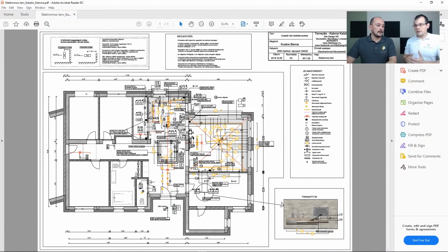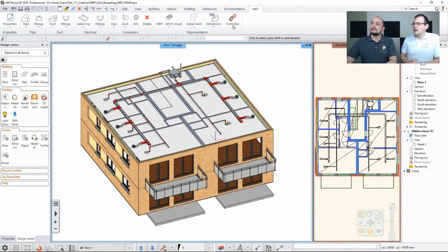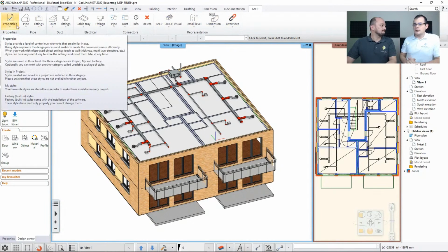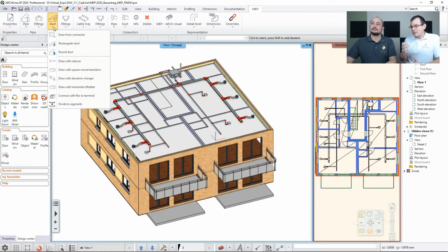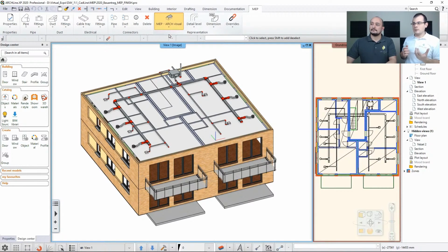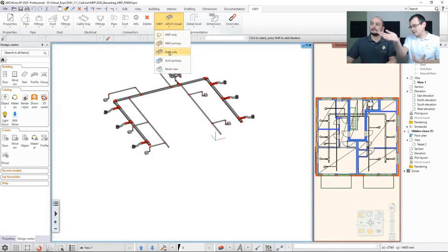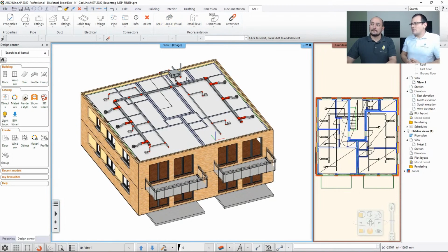I was just asking that if you can do this with lighting elements and wiring, then maybe you can do the same thing with piping. And this gets us to another topic, MEP, mechanical engineering and pipe management, which is another discipline that ARCHLine is going into in addition to architecture, of course. If you want to create a schematic view of an HVAC system, for example, like the one you see on the screen, then you can do that. Now, the special thing is that you can import the objects from an external source, like you did with that heat exchanger, and then you can build up a network using semi-automated elements.